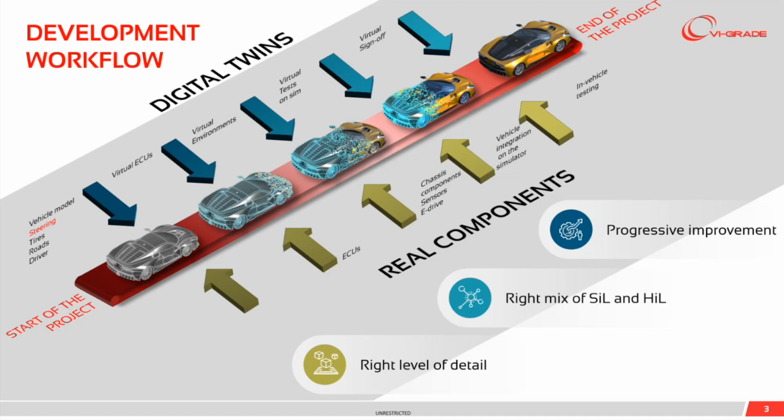Thanks to the increased capability of real-time simulations and driving simulators, we can stretch those development cycles, starting with a proper model in the loop, and then, as soon as hardware becomes available, at any time it can be replaced by hardware in the loop, and also a mix of model, software, and hardware in the loop, to achieve the goal of development, calibration, and fine-tuning of the system.